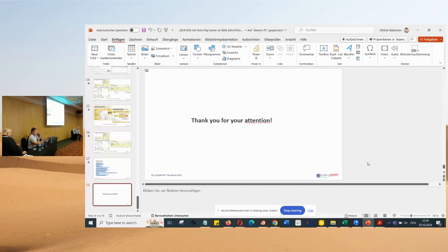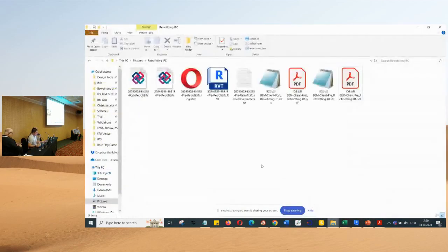By the way, if you're not aware, the IFC schema has occupant-related information, like properties. If you rent your house, you can also add that into your model, and you can add additional information. What type is a building? By the way, we also captured that one. Before you go through, let's go check the IDS, how it looks like. Let me open the IDS that we created.